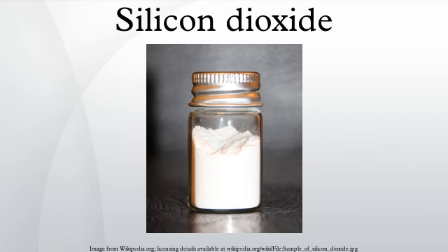This property is used to grow single crystals of quartz in a hydrothermal process where natural quartz is dissolved in superheated water in a pressure vessel that is cooler at the top. Crystals of 0.5–1 kg can be grown over a period of 1–2 months. These crystals are a source of very pure quartz for use in electronic applications.